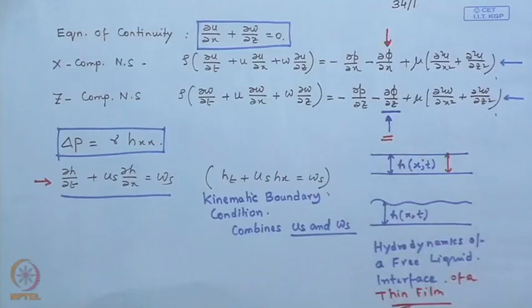If your film thickness is higher, h will have some exponential power and be in the denominator. So for higher values of h, phi will tend to 0. Therefore, this term has no significance in the macroscopic derivations, and we often tend to neglect it, but there is absolutely no problem if you have this term intact in your macroscopic derivations as well.